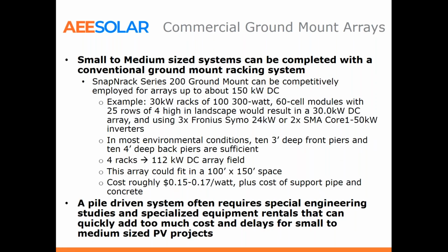Now, with that being said, we do still see quite a few installations using our Series 200 ground mount. So this is a 4-high landscape system, and very economical, up to about 150 kW before you start considering something like a pile-driven system, which we'll talk about in just a minute.